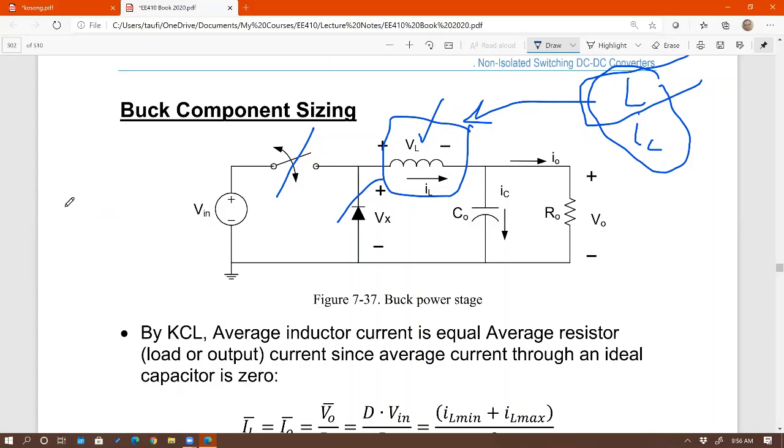What's going to happen is that under the non-saturation region, or linear region, of this inductor, the inductor current, as you know, looks like this, a triangular waveform. But if it's under saturation, if you exceed that IL peak, it's going to look like this.